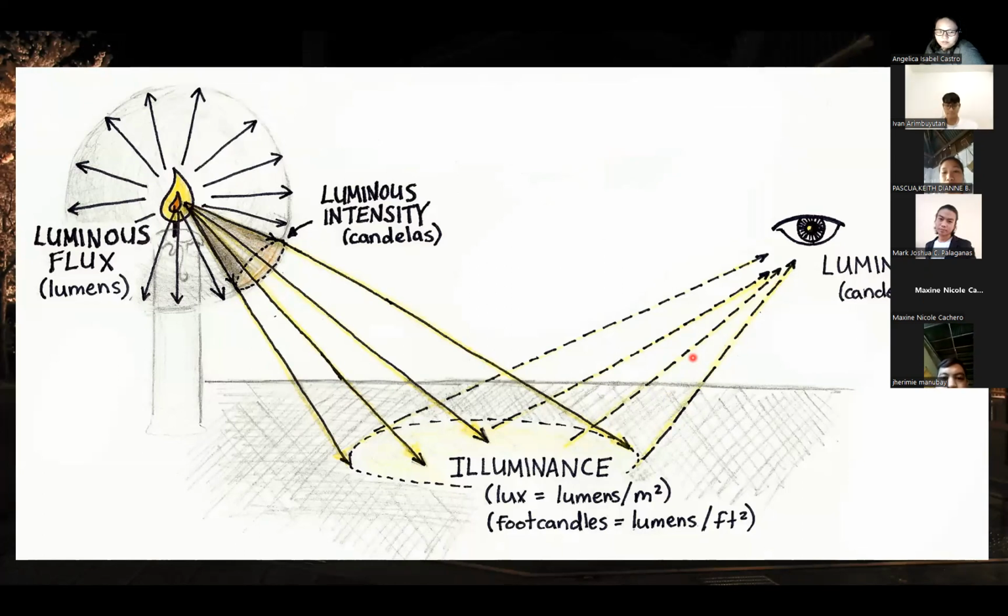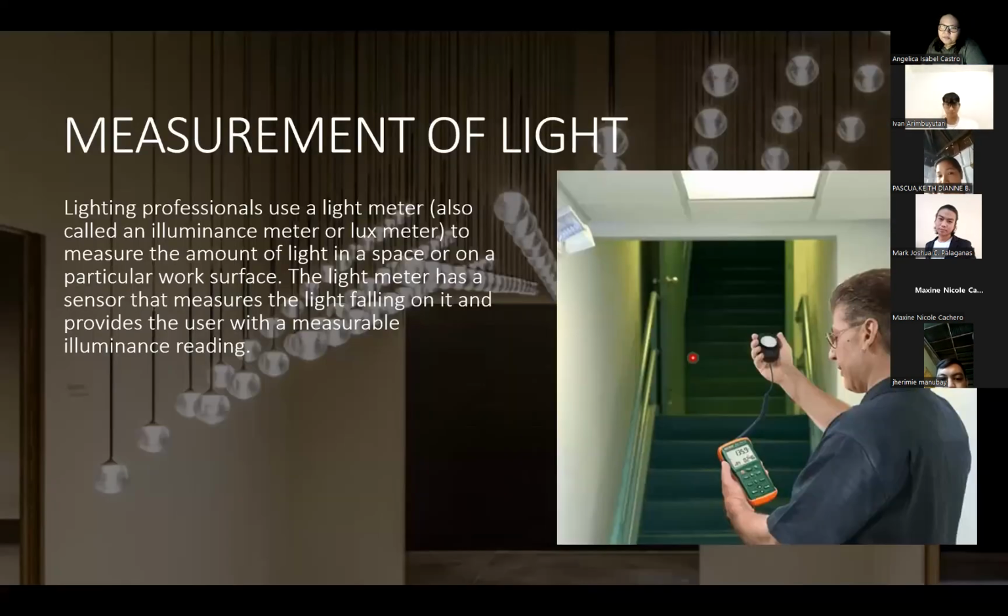So I'll give you time. Yan siya. Inulit-ulit na natin ha. Luminous flux, measured in lumens, kung gaano siya kalakas. Intensity is what we perceive, that's measured in candelas. The illuminance is yung rate niya na ma-measure talaga natin. Ma-measure talaga natin yung lux, mga kaibigan. Huwag kayong mag-alala. Na ma-measure natin yung lux, we use this kind of device. This is what we call a lux meter.